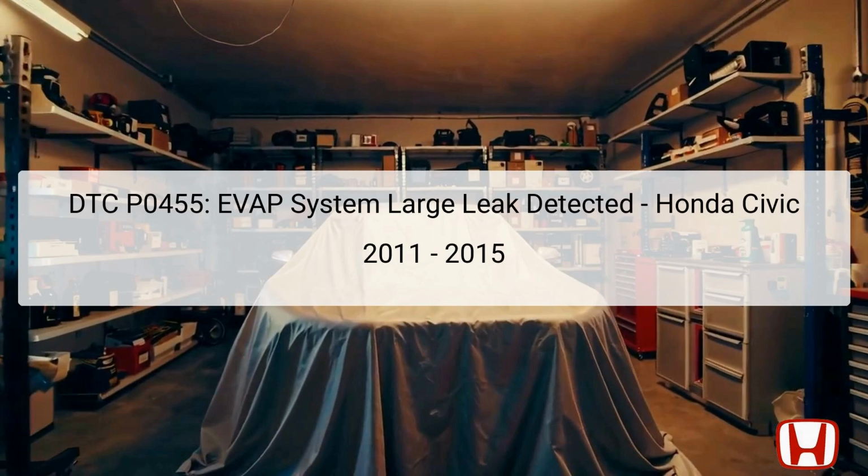The DTC P0455 indicates a large leak in the Evaporative Emission Control System, EVAP, of a 2011 to 2015 Honda Civic. This system plays a crucial role in capturing fuel vapors from the fuel tank and preventing them from escaping into the atmosphere. Key components involved in this system include the fuel fill cap, EVAP canister, fuel tank vapor recirculation tube, and associated valves. Mismanagement or damage to any of these components can trigger a DTC P0455.